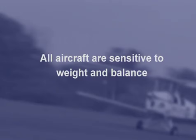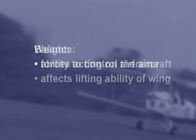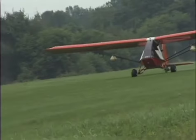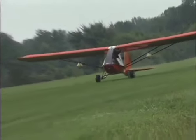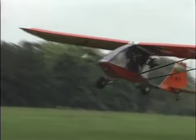To start with, all aircraft are sensitive to weight and all aircraft are sensitive to balance. Weight is the forces acting on the airframe and also affects the lifting ability of the wing. Balance is your ability to control the aircraft. So you've got to consider both of them. When they design an aircraft, they design it with a maximum weight in mind, and you don't want to exceed that, or you're going to overstress something in the aircraft.